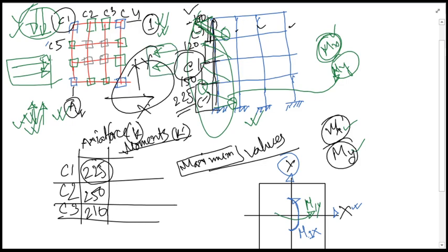So for this directional lateral force you will be obtaining one maximum bending moment, and for this directional lateral force you will be obtaining another bending moment diagram, and from there another maximum bending moment. So from this one and that one, the maximum bending moment you will be getting for C1 will be denoted as My, and the maximum moment you will be getting from both of these two diagrams, you will be sorting out the maximum moment amount, and you will be getting that as Mx.